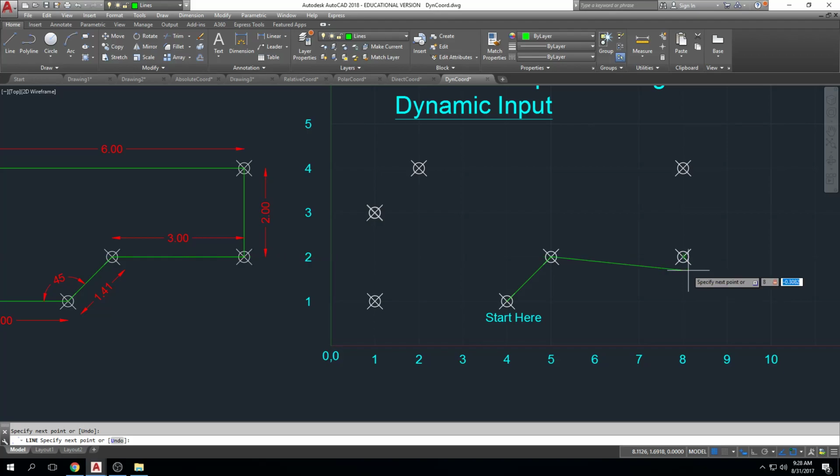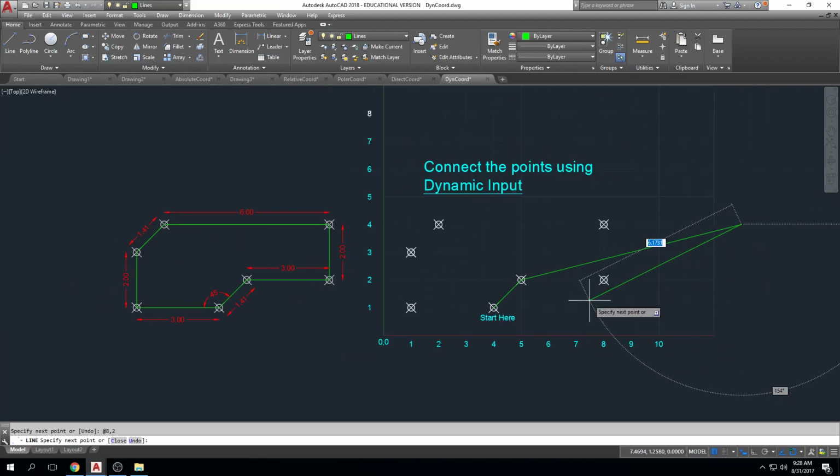Now I'm back to the 8 at the cursor, and it's locked that 8, and I can tab over, if it didn't bump me over, to where it's highlighted in blue, and I could type 2, right? Well, why it did that was because my cursor was kind of angled at the same time I did that. So when I finished it, it went into polar and gave me an angle, right? So I feel like it's a little bit temperamental.